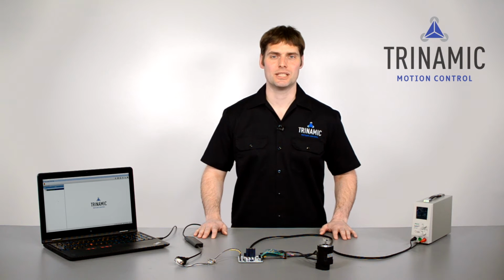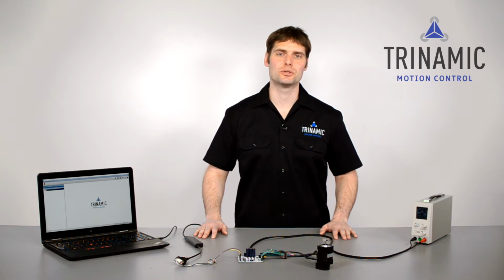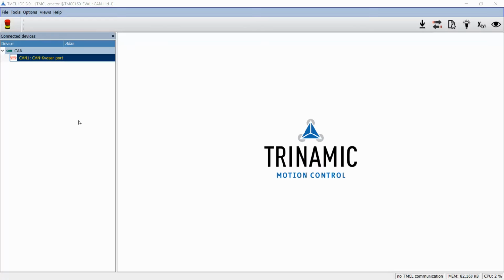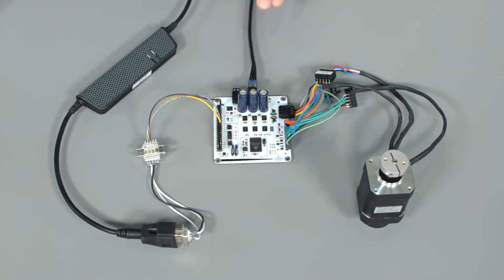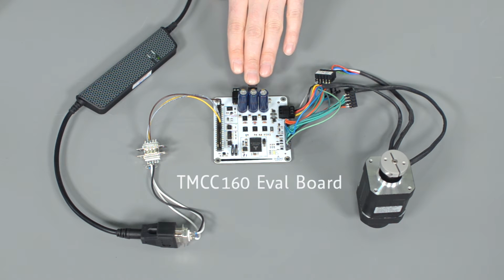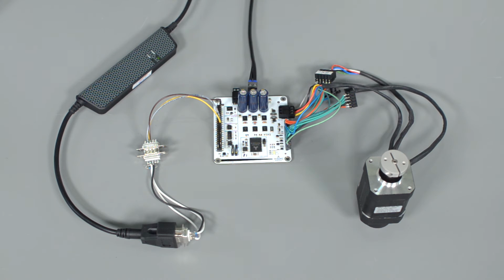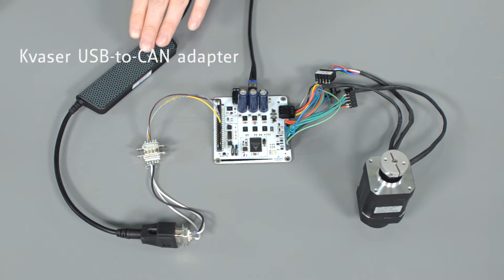I'm System Design Engineer at Trinamic, and today I want to show how to use one of our brushless DC modules with the TMCL-IDE software tool. For this video I use the following setup. I use a TMCC160 evaluation board and a motor with Hall sensor and encoder. For the communication with the TMCL-IDE, I choose a Quasar USB to CAN adapter. This is one of our supported CAN interfaces.